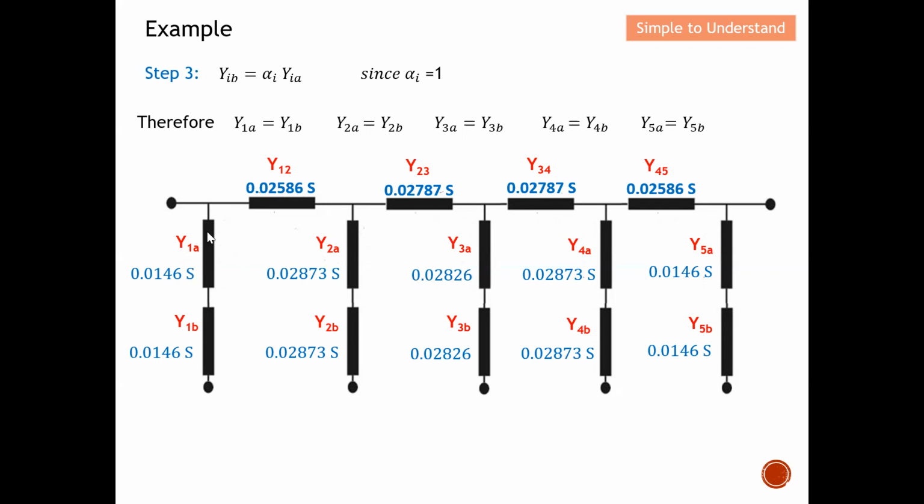Now instead of a quarter wavelength, they become a half wavelength with an open circuit at the end of the terminal. This is how I calculate or design the open circuit stub in order to achieve a pass band centered at 2 GHz with a fractional bandwidth of 0.5. Hopefully this is clear.